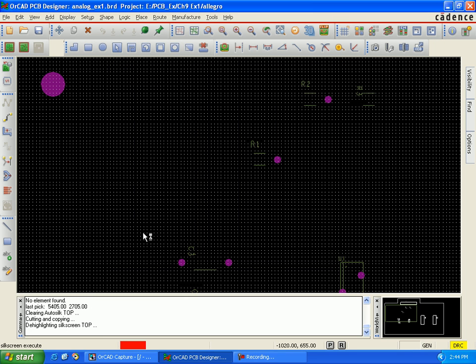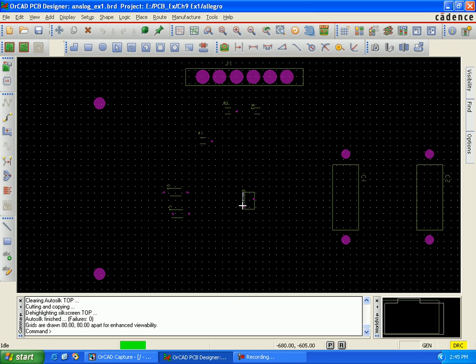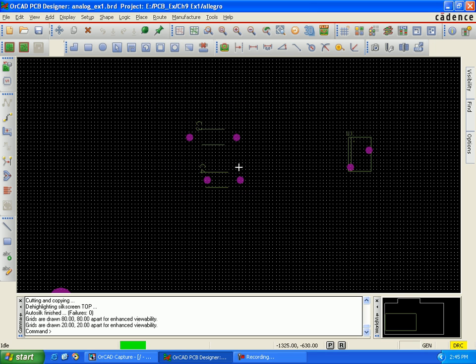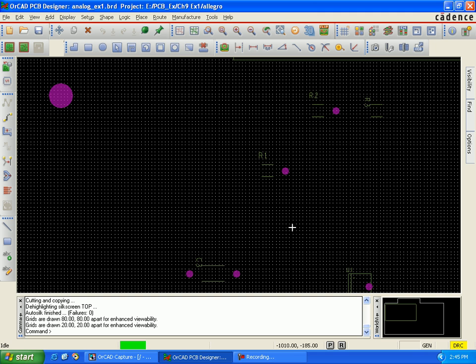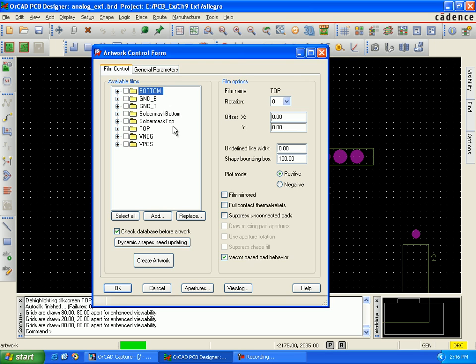Setting up on the top layer, we're going to define a layer called silk screen. So this will be around the component, stating that at that particular location we have to solder the C1, C2, R1, R2, R3, C3. We're going to make changes over here. This one is now R1, R2, R3 is okay. J1's outline, this one is the J1.